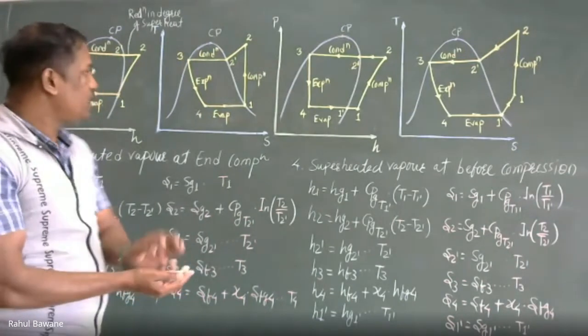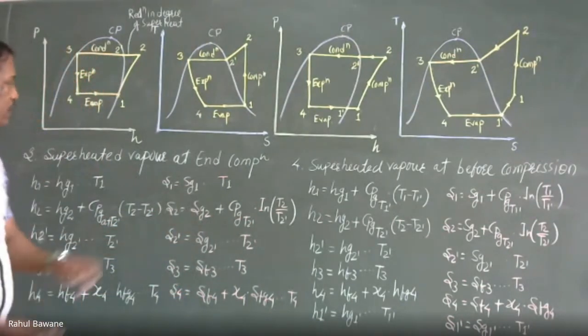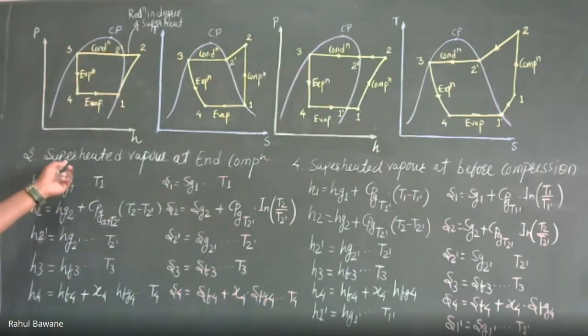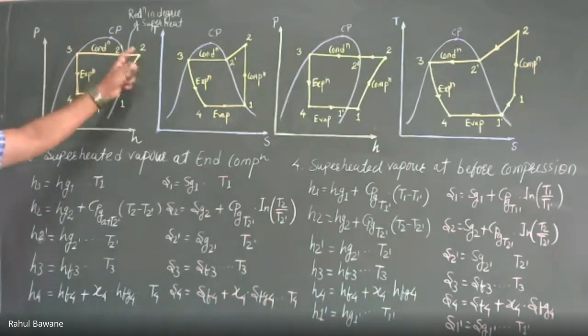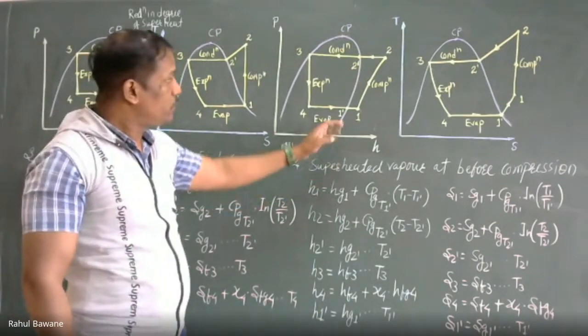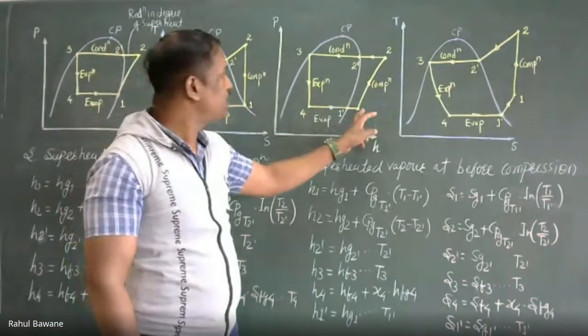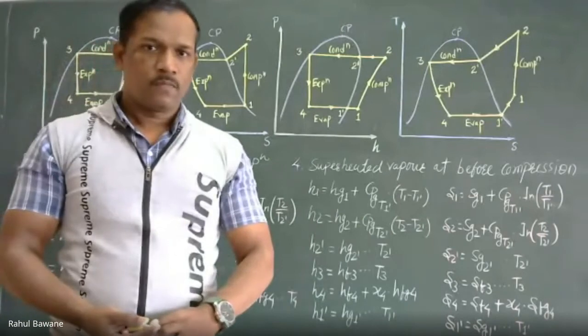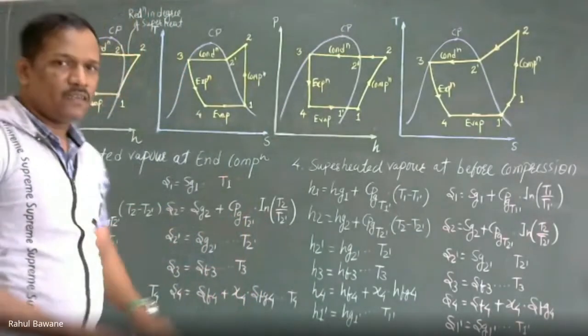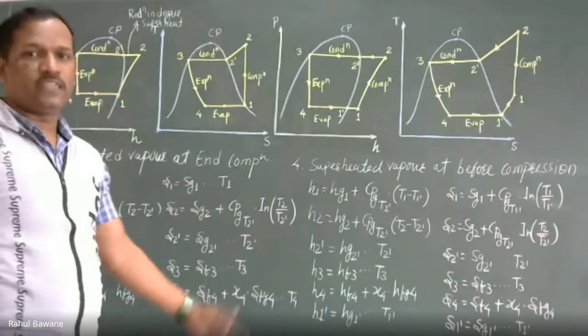So these are the two conditions: first, superheating after compression, second, superheating before compression itself, and the last condition, if there is subcooling.